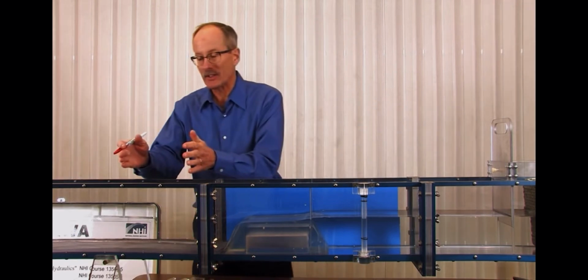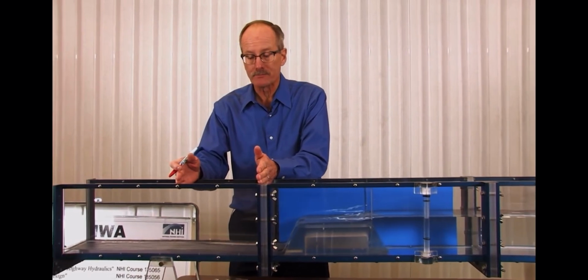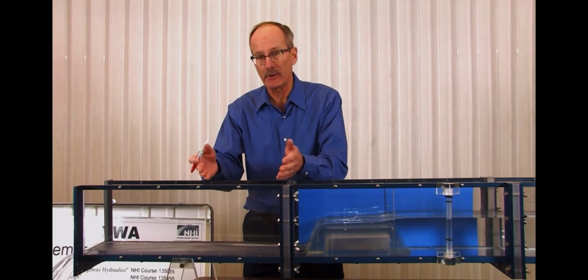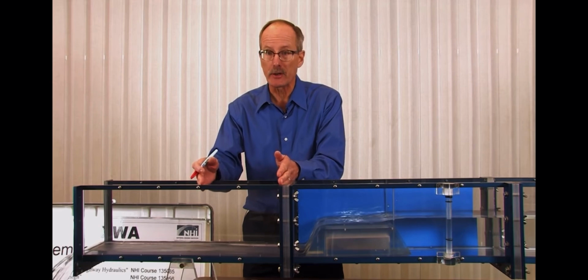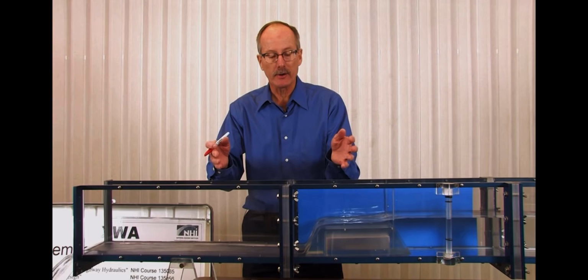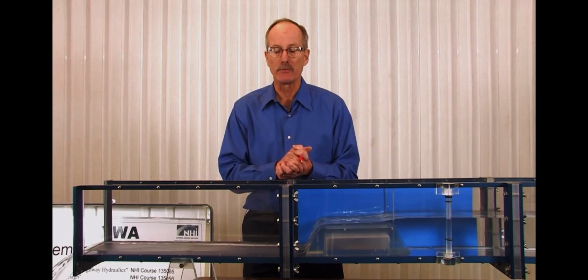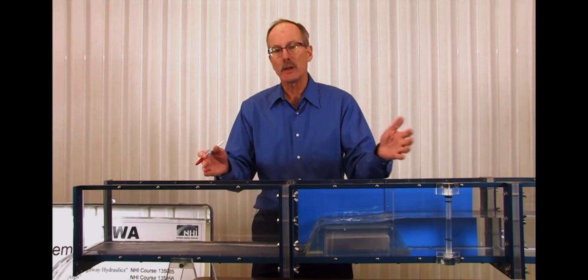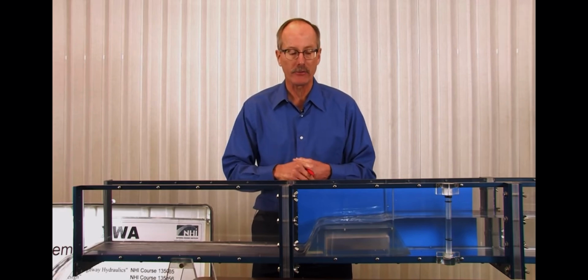In contrast, at the other end of the weir, we have supercritical flow. The flow is very shallow and very fast. The Froude number would be greater than 1. An alternate word for supercritical flow is rapid. So a broad-crested weir creates two flow regimes. Upstream we would have subcritical flow, downstream supercritical, and in between we would pass through the critical depth, typically on the weir crest very near the leading edge.